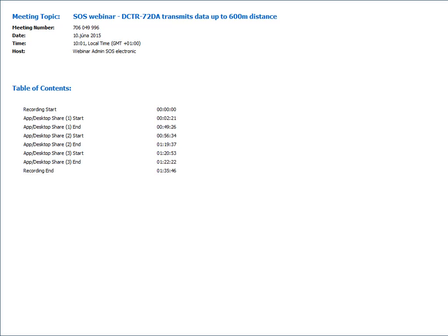If you want to use routing, you need to have a network of bonded nodes, and you have to run the discovery. You can avoid creating the network if you want peer-to-peer communication, or if you have a star topology, then you can use the peer-to-peer communication that I showed you in the presentation.